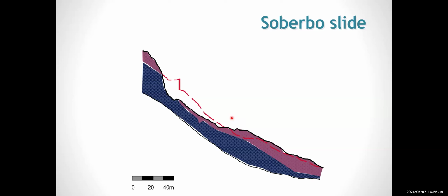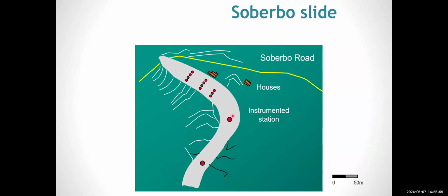Until then, there were a few boreholes, but they were all vertical. And then they decided to carry out some inclined boreholes to study this. And what he found was a diabase dike. As a matter of fact, a family of diabase dikes. They were absolutely unweathered, okay, in a very weathered mass. So what happened was that it was like a dam. The jointed rock here had a very high permeability, and when the water came to this point, the water pressure would rise when it rained, and this was the cause of the movement.